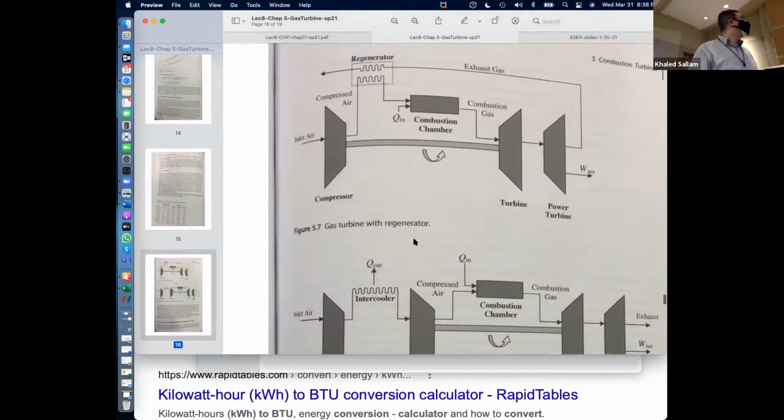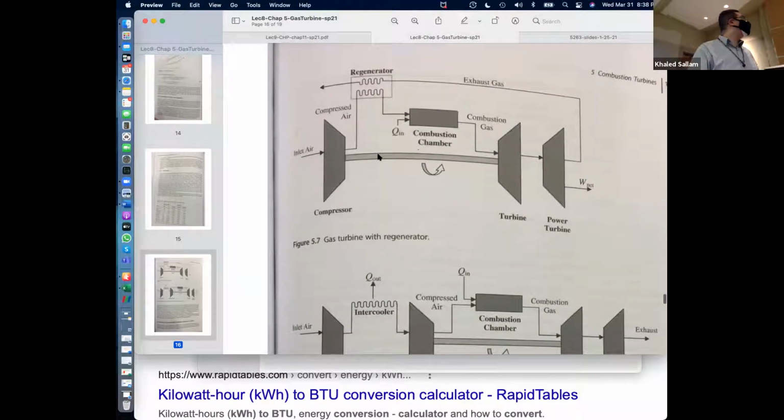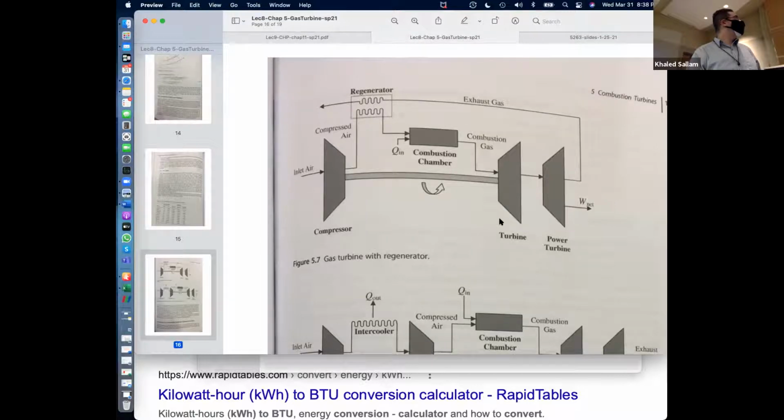Okay, so here's how they can make the gas turbine really competitive. What they can do to make it go up to a good efficiency. They can do this. This is called regeneration. What is happening over here? They realize that the exhaust of the gas turbine is most of the time way hotter than what is going into the combustion chamber.